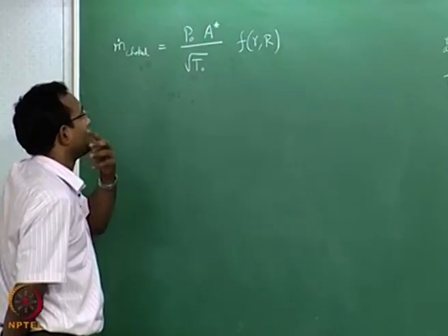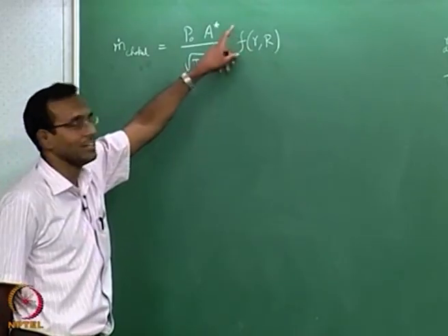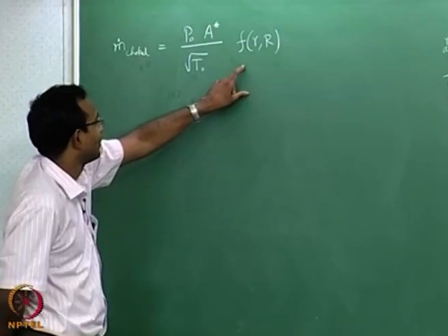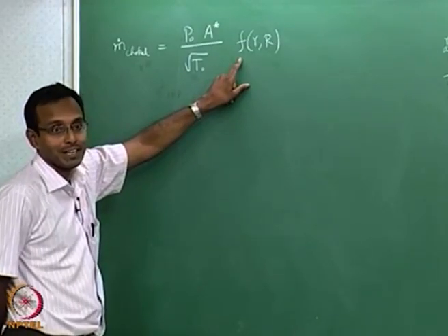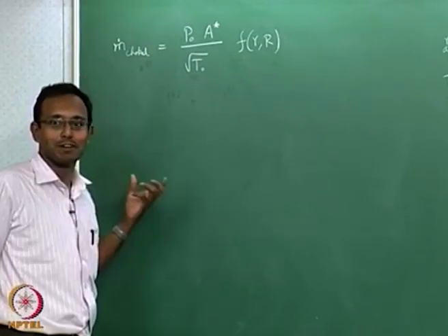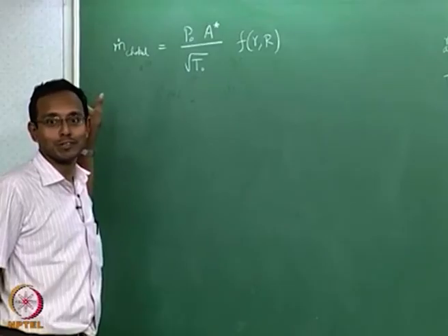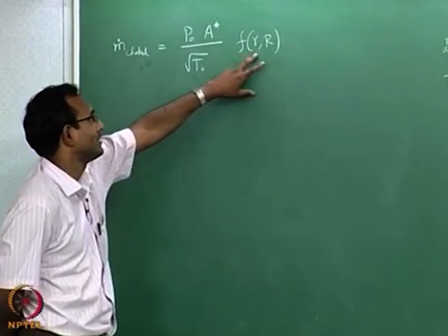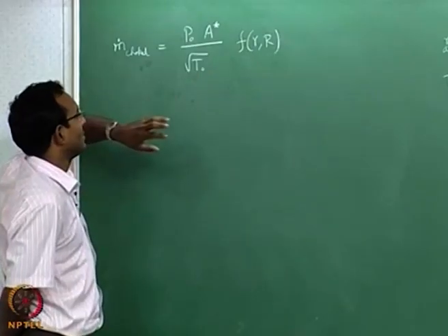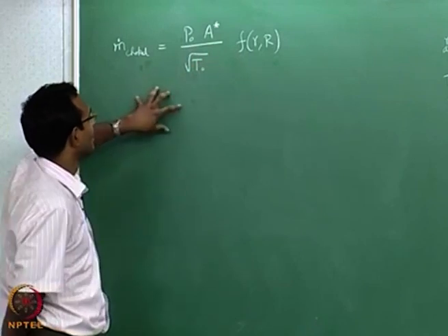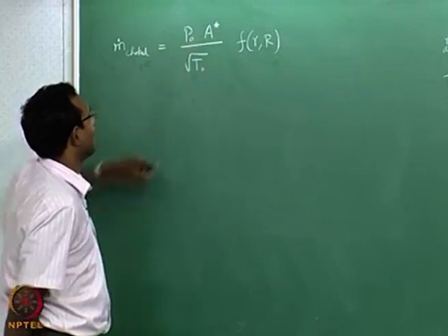Of course the R is in the denominator of this function, 1 by square root R is the function inside for R. If you think about that, if I increase my molecular mass, my mass flow rate increases. That is just because it is heavier molecules going through, so there is more mass going through. We won't worry about that aspect. We want to think about only compressibility, that is related to gamma in here. And we already discussed that in detail separately in each of those cases, so I won't discuss that in here. I will just look at these individual values.